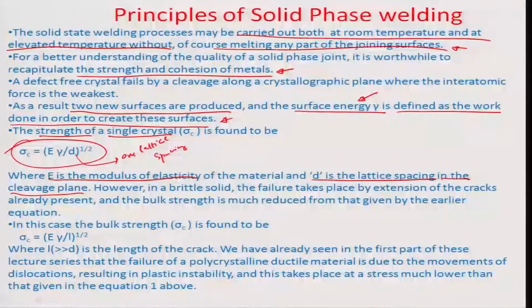And think of it that in brittle solids the failures take place by extension of such cracks. So, if some kind of a twin surface pair is created, it basically extends itself in a certain direction, and we say that this is because of the crack propagation process. So, along that particular line there develop several such interatomic spacings where a new surface starts getting created. Okay. And so, a complete cleavage plane is formed, which may be more than a few lattice spacings in length.